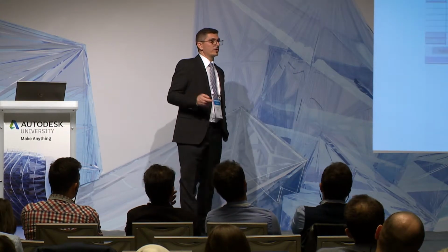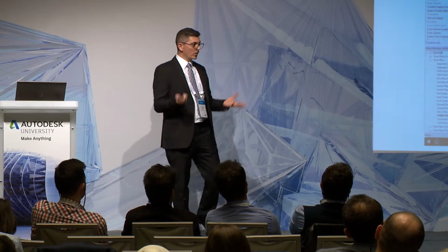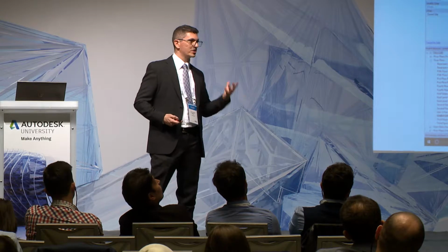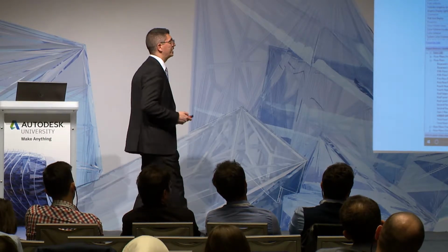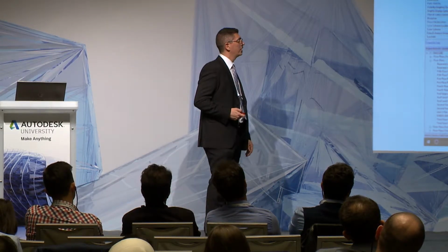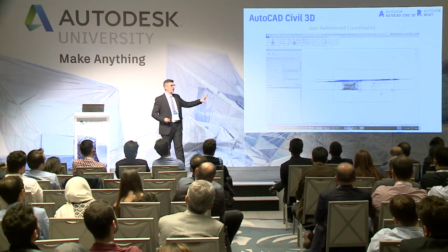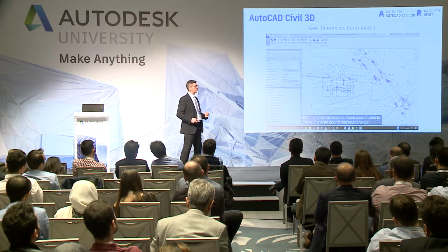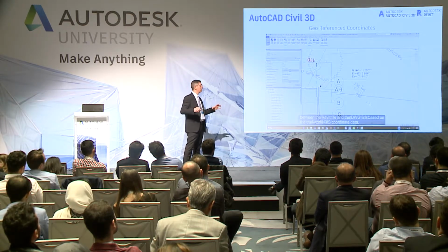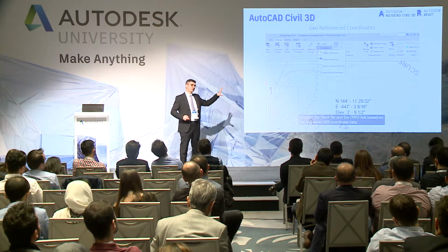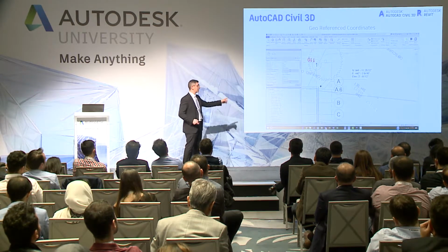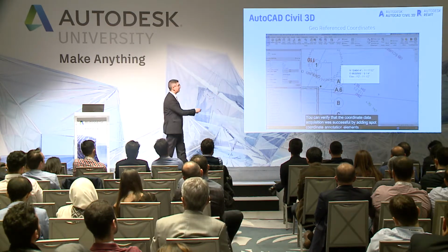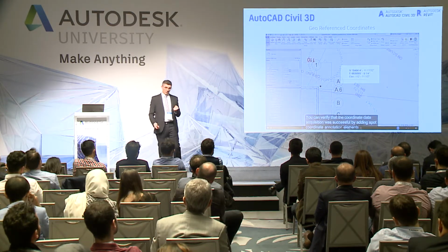One of the important things about this workflow is georeferencing. We are starting from GIS data. We are starting from InfraWorks. You know that in the last version of Revit, we have the possibility to manage the georeferencing tool very easily. And we have the possibility to load the coordinates of one DWG as a reference inside Revit, like this one. I can select the reference. I can move and rotate it to the exact position, and then I change immediately to acquire the coordinates of the source DWG.